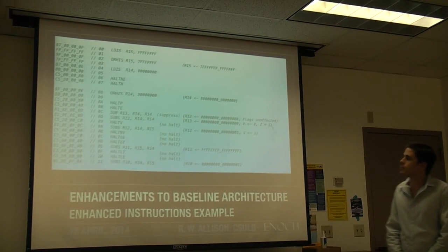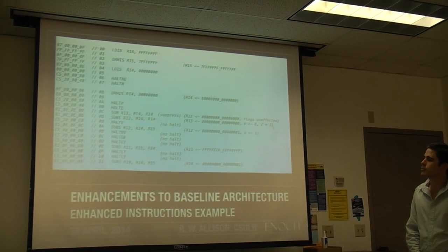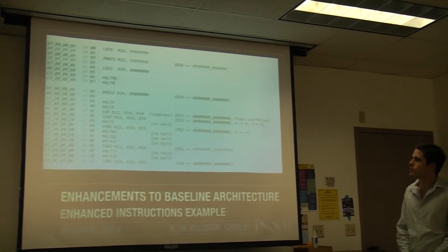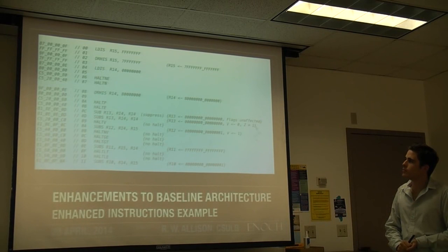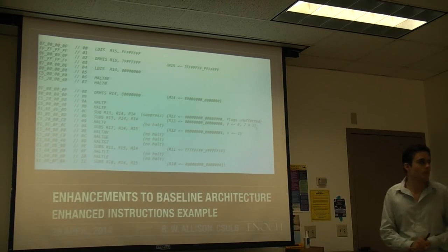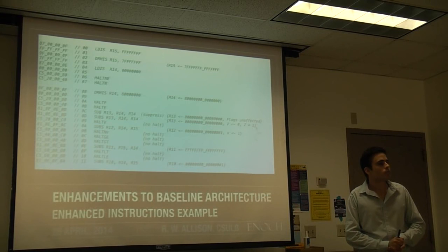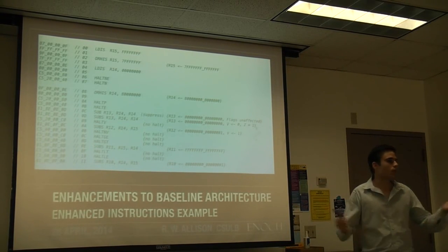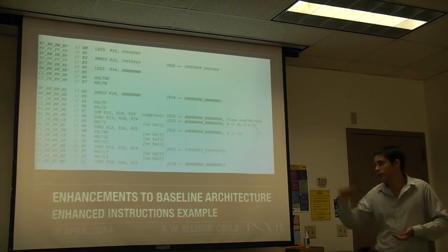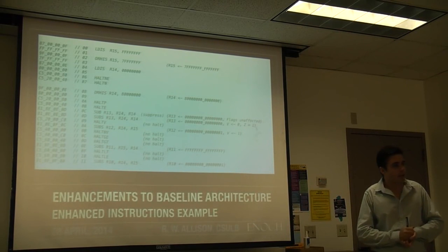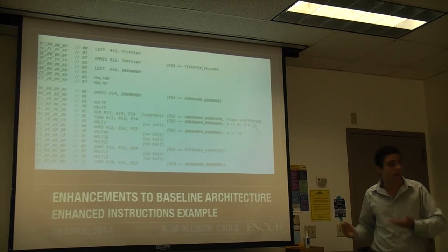So you actually modify the instruction itself. What you write is a load immediate. In our example, we have a halt if positive. That's actually within the instruction. We use the bits within the instruction, so it's not a different mode. It's actually a different instruction altogether. Like a halt, it just puts almost everything to zero, the default state, and does nothing. When we have a halt if positive, we have to check in the decode state whether or not the flag bits from our flags module indicate that the previous instruction did produce that.